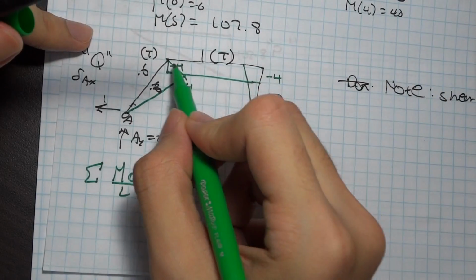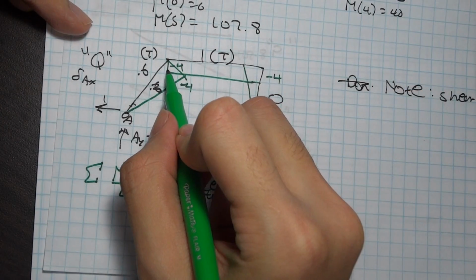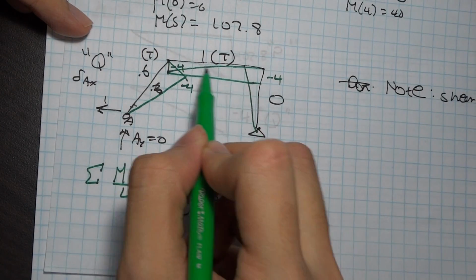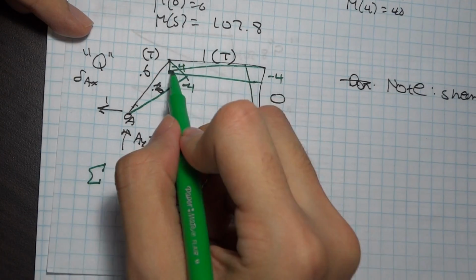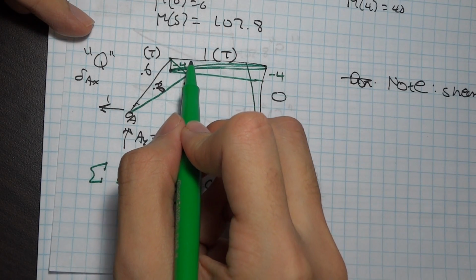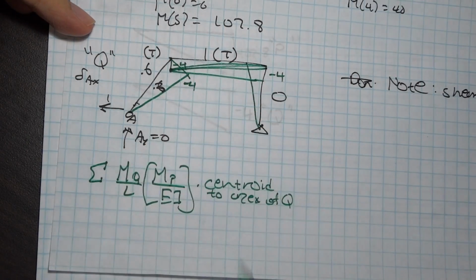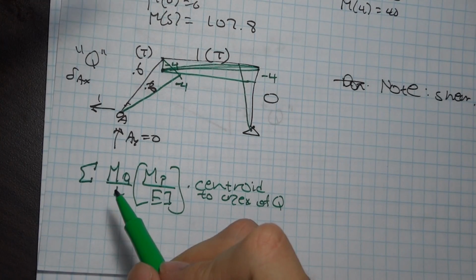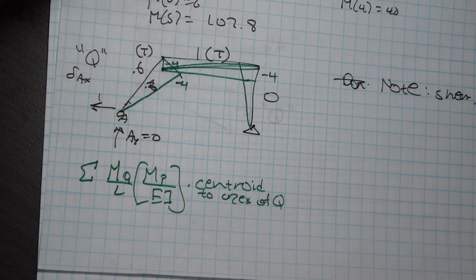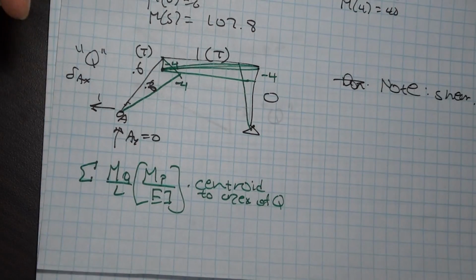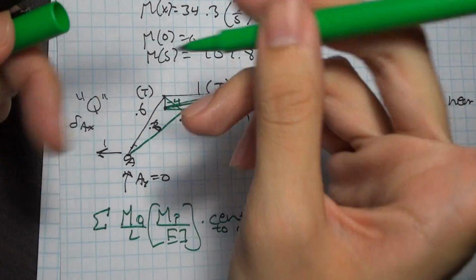They can be any shape you like. So I have a rectangle up here, and this looks like a parabola, but this is actually a straight line. I want to divide into 2 triangles. I have a rectangle, I divide into 2 triangles. I only need to split the Q diagram into triangles. The P diagram can stay as fine as it is.